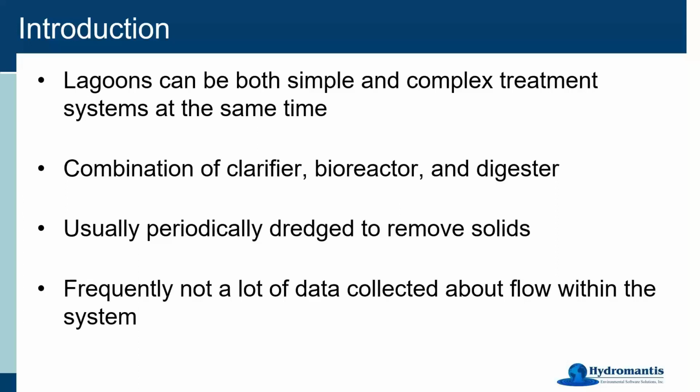They act as a clarifier. They're settling out solids over time. They are a bioreactor, particularly the aerated ones. They're there to actually grow some biomass and do some treatment. And of course, in a lot of cases, they are also serving as a digester. When those solids settle out, they can form an anaerobic zone across the bottom of the lagoon, and then therefore you can get some solids digestion happening there too.